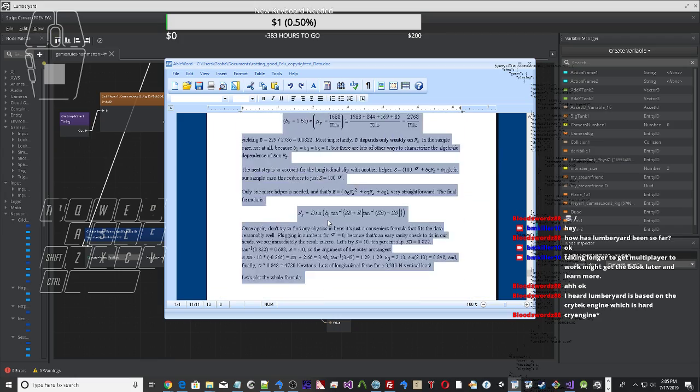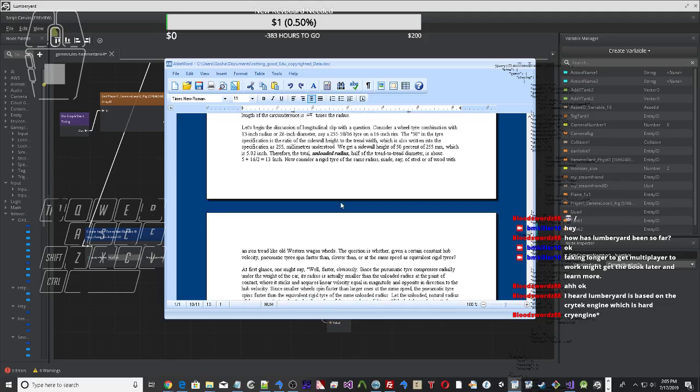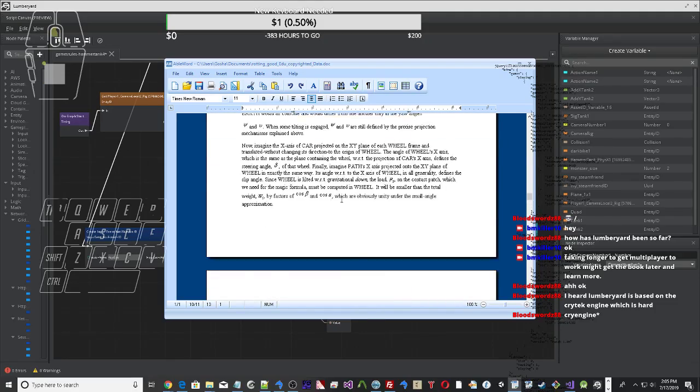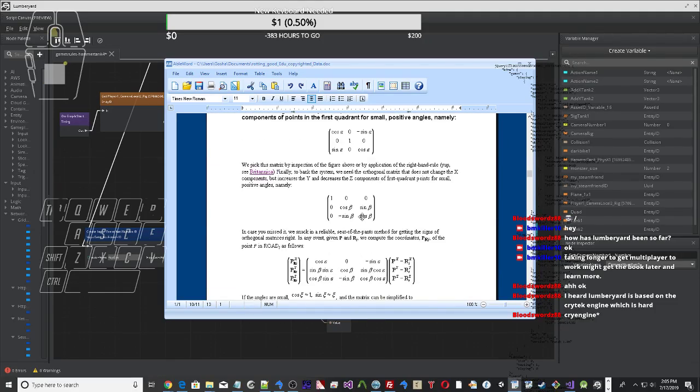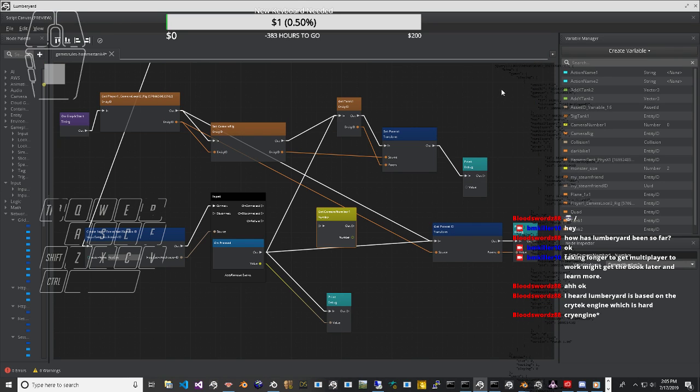We write longitudinal slip as defined by the actual angular velocity of a wheel plus tire under braking or acceleration, compared to the corresponding angular velocity of the same wheel plus tire when rolling freely. We write the free-rolling angular velocity as v/r, where v is the current, instantaneous velocity of the hub center line of the wheel with respect to the ground, and r is the effective radius, a constant defined below.